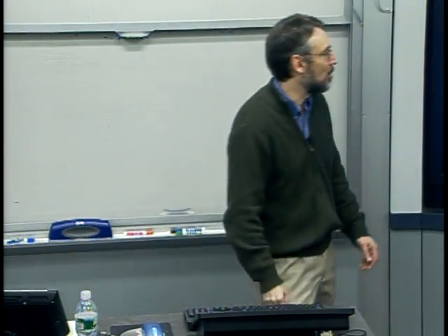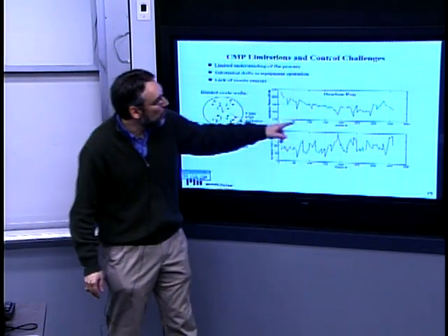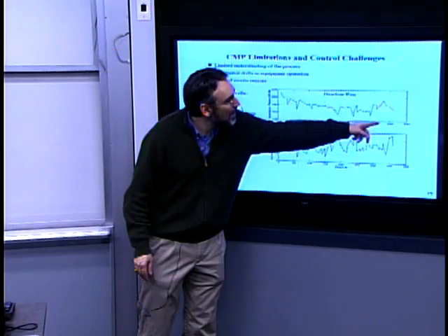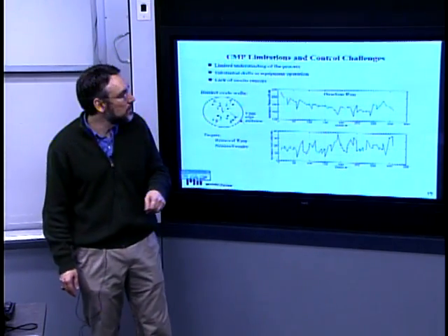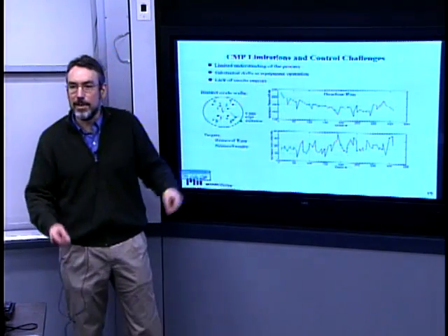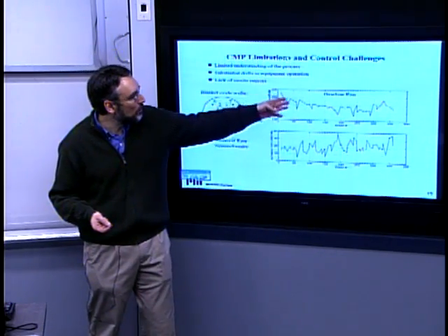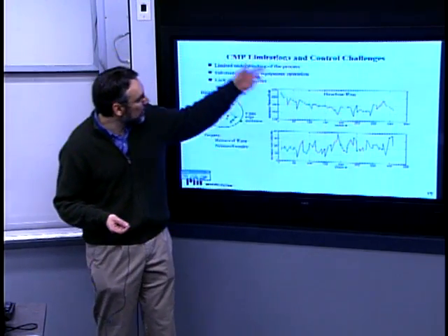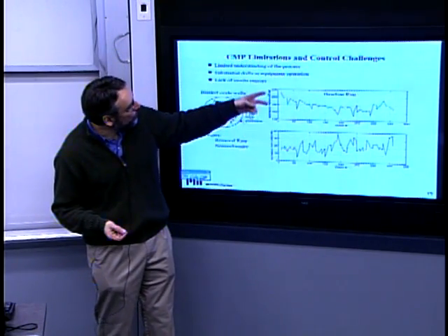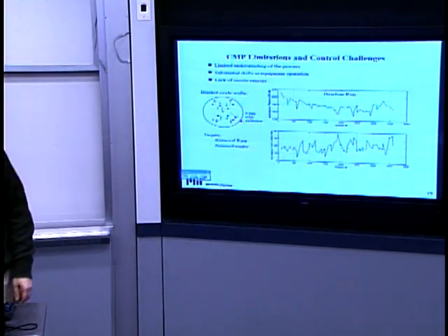The process and the equipment changes its state over fabrication as well. And if you looked at the normalized removal rate for a 350 wafer sequence, you will often find drift in the removal rate. You might start out with a fairly high removal rate, and over time it drifts down. And this is something like a 20 or 40% kind of drift.